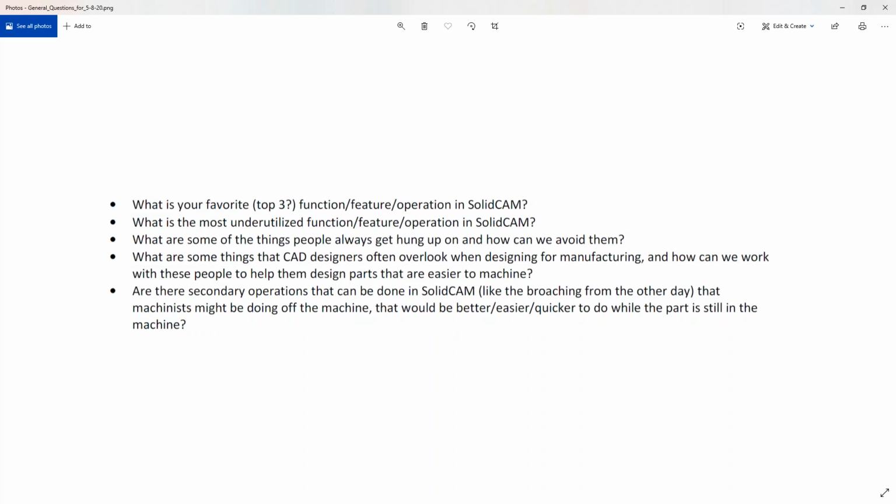And it does a lot of the work for you, because if you don't use that, you're looking at doing some sketching to limit the travel of the tool. You're trying to tell it exactly how you like to go around. Whereas if you just do 3D iMachining, you can say, here's my part, here's my tool, figure out the nooks and crannies, and then I'll give you another set of tools if you need it to go a little deeper into the part. A lot of times it's basically a set it and forget it situation. You just say, here's the tool, here's the part, do it.